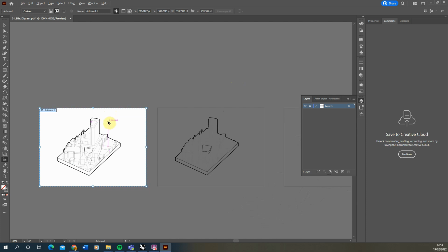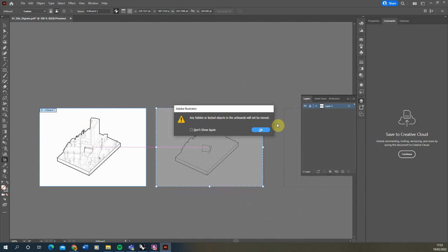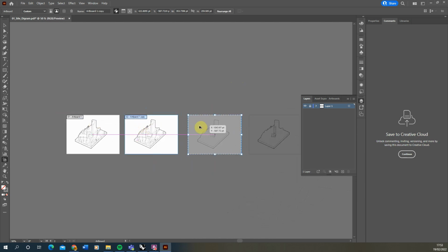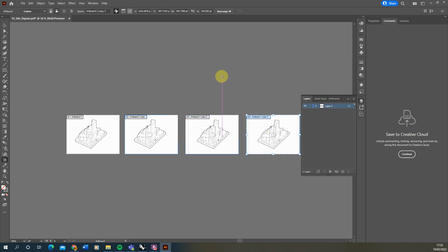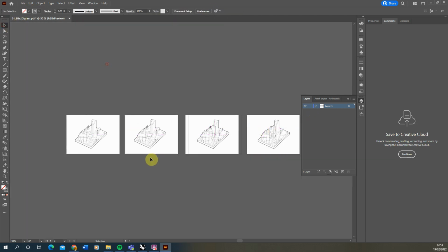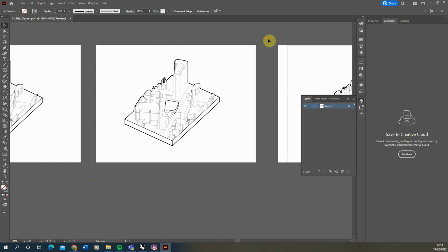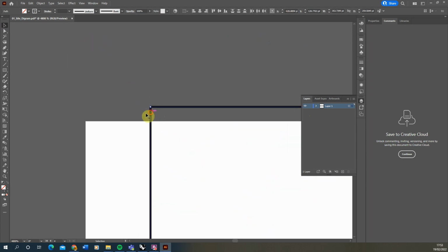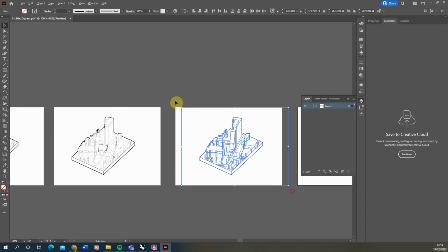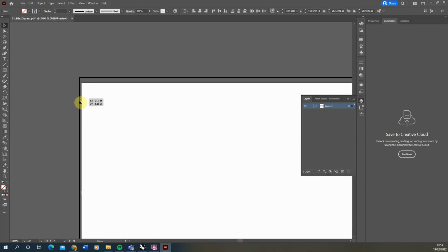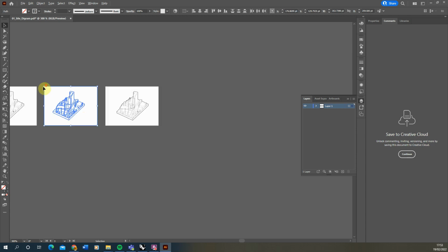Once we've got that, we're going to hold the Alt key down and just click and drag the artboard. I'm not going to try and line it up at this point. I'm actually going to just copy it over first, and then we're going to line up the objects afterwards, like so. Then we can unlock our tab, click off the artboards and line up our objects to our board. I'll usually try and find the top corner and snap it on like so. You just want to go around and do that for all of these, so they're all snapped into place.